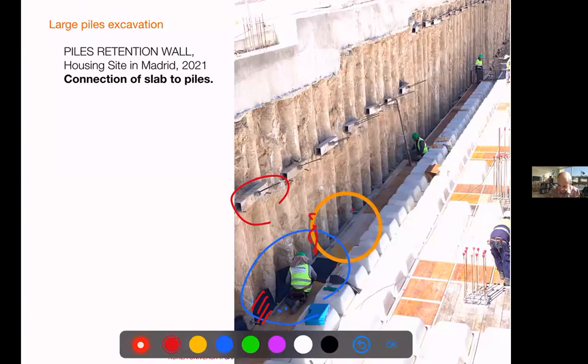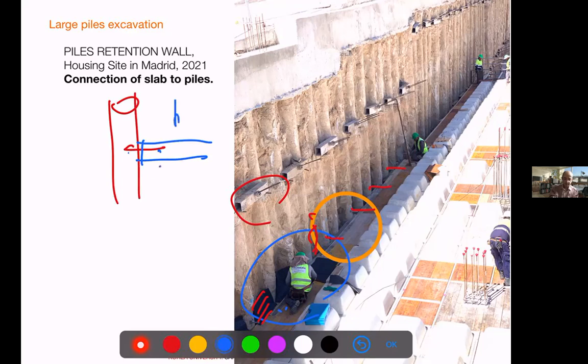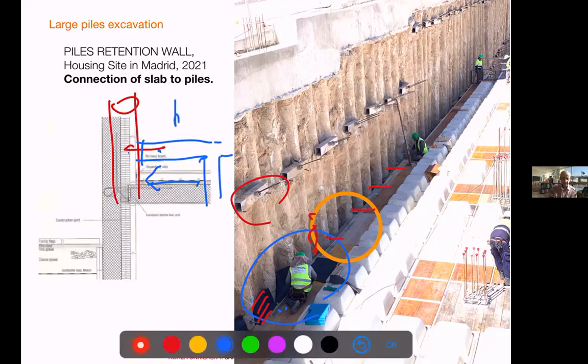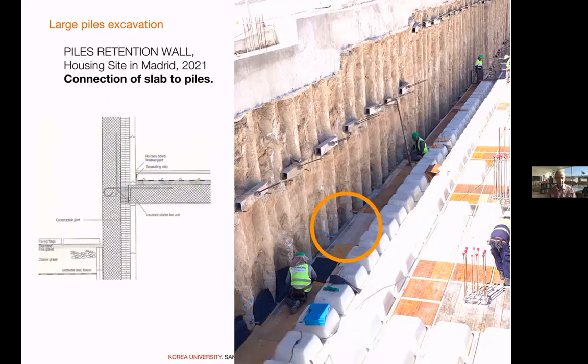These are the steel rebars drilled. And in this case, they're put in every 1.5 meters. That means the load is very small, right? This is drilled, put the steel, and then when we put the concrete, so you have the pile, the steel, and the concrete poured, and it will be supported by those rods, right? This is why this span is a bit smaller, so the load is not so big. This is what we saw before in the detail of the basement, right? This kind of connection every field.